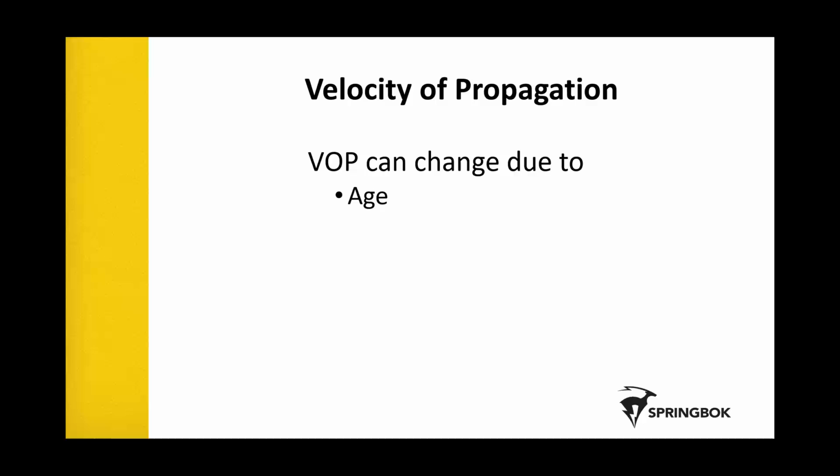Age of the cable. Should stand to reason a cable that we buried 20 years ago is going to behave differently than one we just put in the ground last year. And I don't care where you're at, I'm quite certain you got cables a lot older than 20 years, okay? Temperature is probably going to be your biggest offender. It is going to be your biggest offender. And when I talk about temperature, I'm talking about temperature changes.